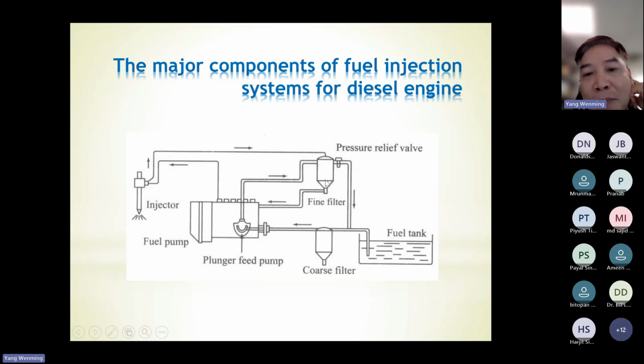There are also fine filters. This one can further remove the smaller particles contained in the fuel. And the pressure relief valve can return the uninjected fuel from the fuel injectors to the fuel tank to avoid overpressure.